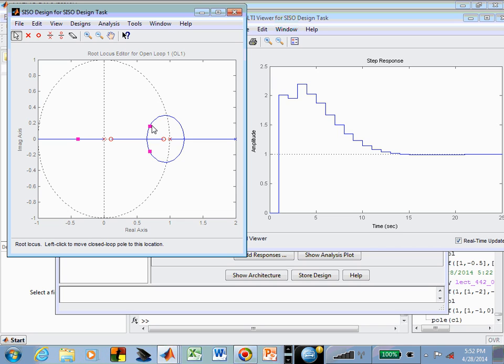What's the deal with the notch at 3 is it's just probably getting kicked a little bit by the changing input because of this pole over here on the negative real axis. So it's not giving you the normal, what I think you were anticipating, this more normal second order behavior. Now you sort of get kicked partway through that first bump, and you start to increase at 3.